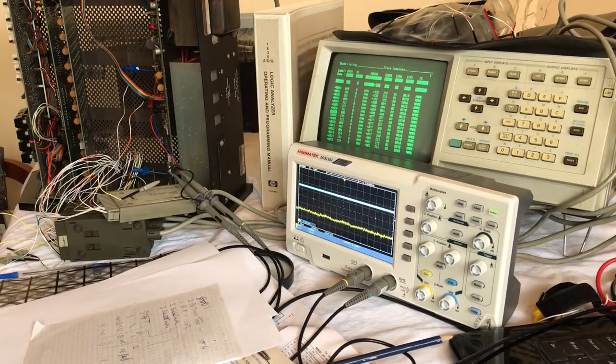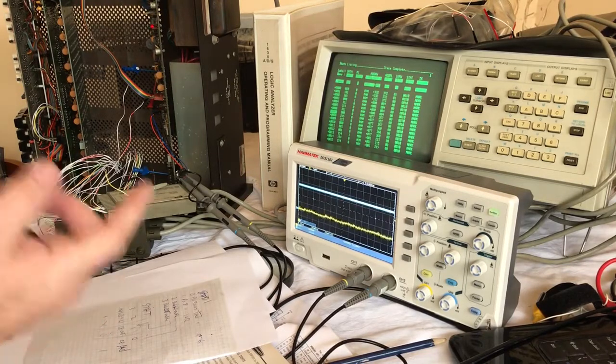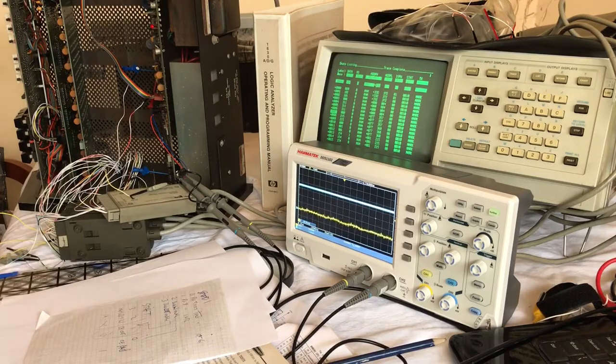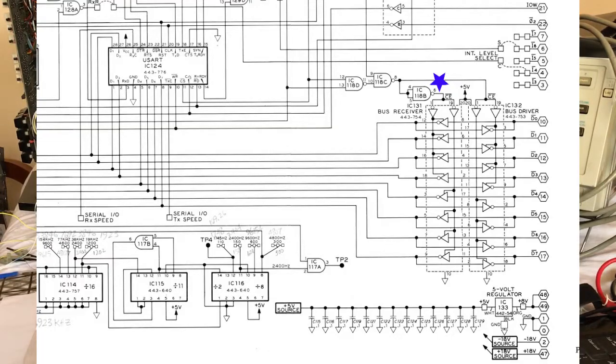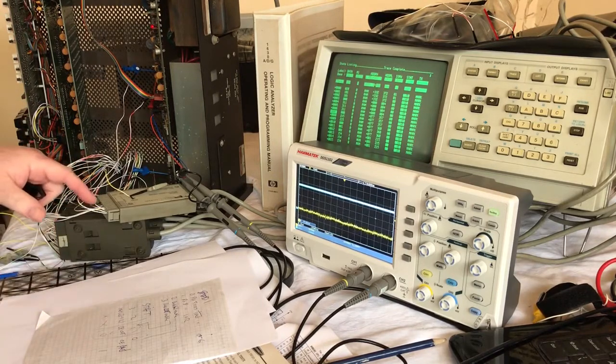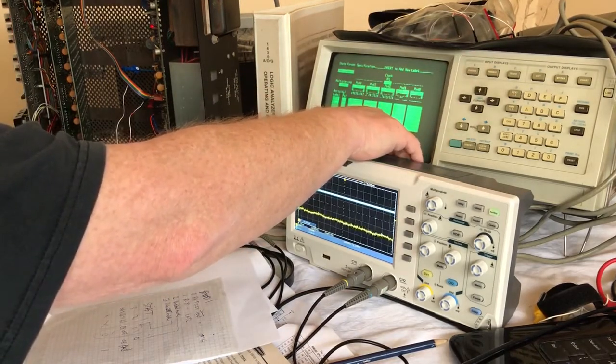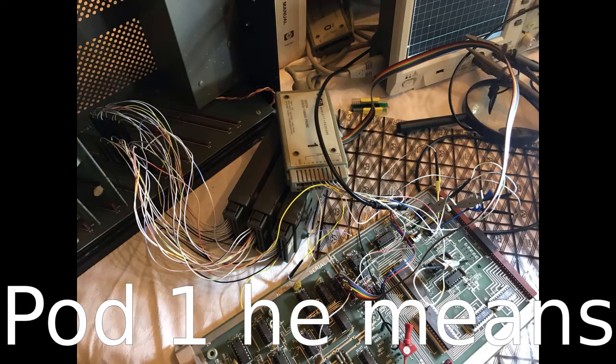That's the CE chip enable out on that pin, which is the data in enable. So we see it, but we don't see a write back out onto the data bus from the output of pin 6 on IC118. Pin 6 on IC118 is the blue wire here, which is just checking, goes into the 2 on the format, so it will be the second on pod 2, so it's that one.